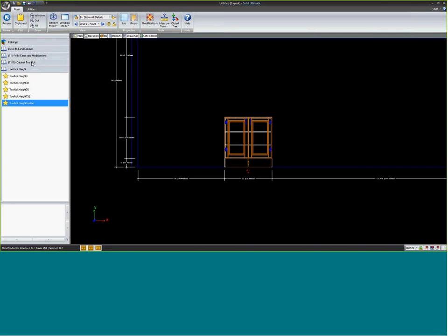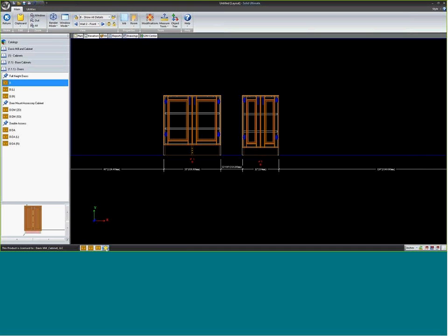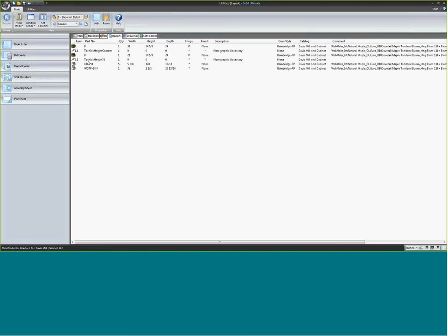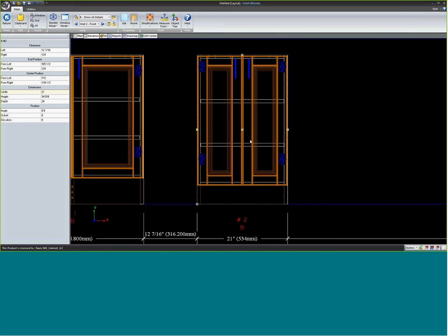I'm going to put one of the wildcards. Let's put a toe kick height 76 down here on my favorites menu. So it's that star icon. If I then go back to my cabinets and I drag a new cabinet out here, and I go and take favorites, this toe kick height 76, and drag it up on this cabinet. Same concept there. Item number 2, toe kick 76. Nothing's changed on the cabinet unless I hit enter 2 times.